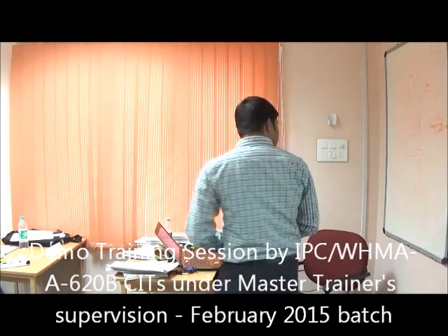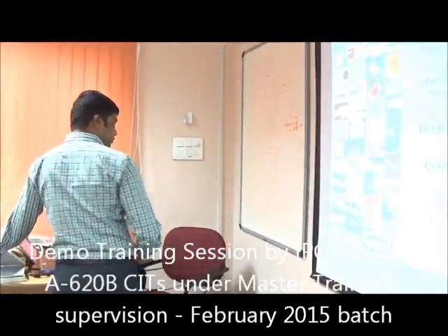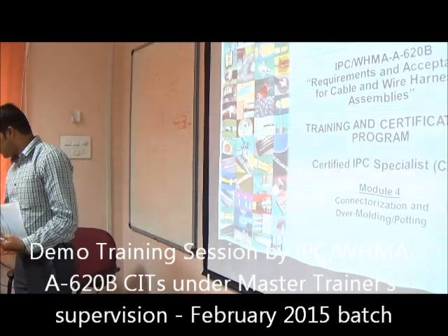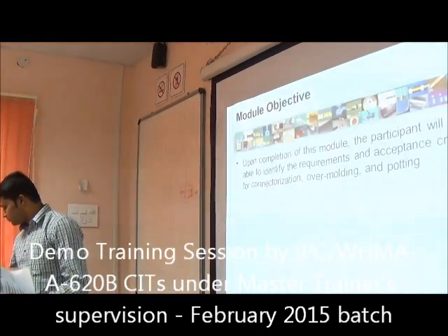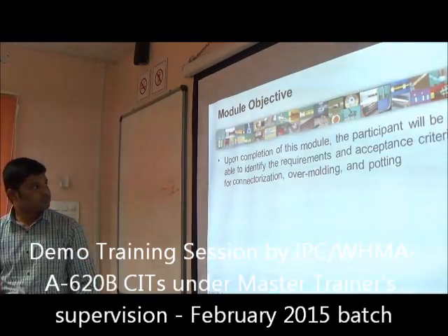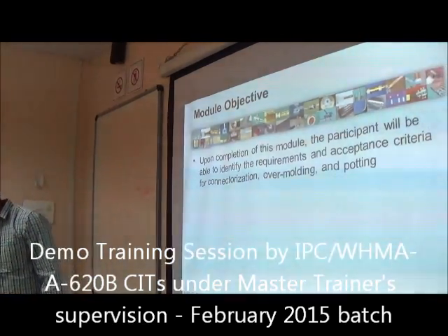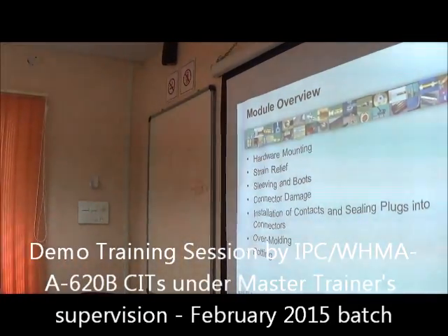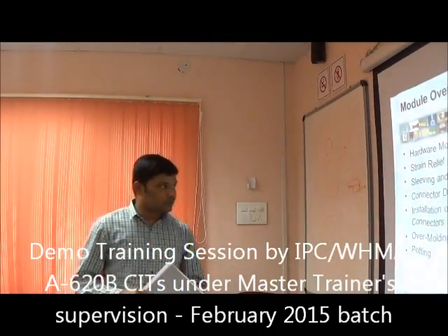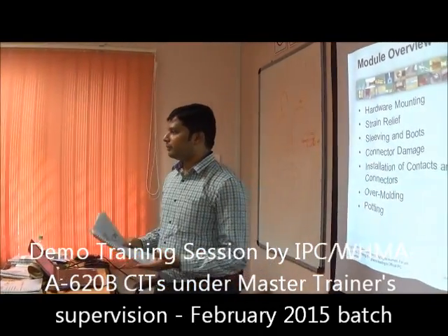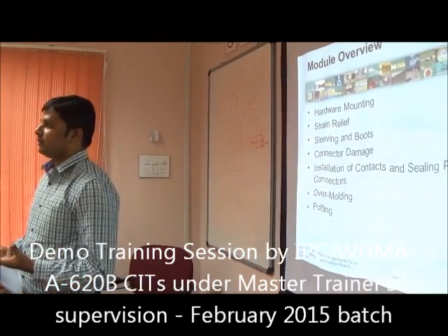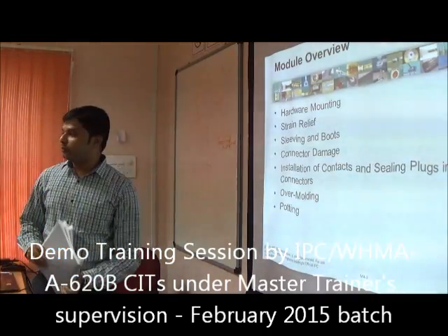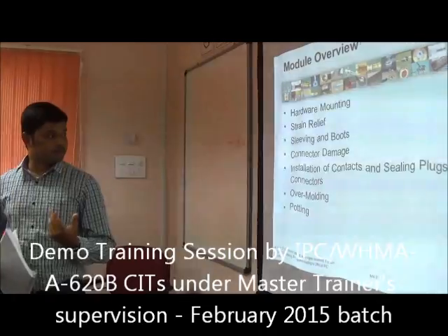So in this particular section, in module 4, which covers section 9, we will be dealing with hardware mounting, like installation of jack post and jack screw, followed by strain relief. In strain relief, basically we use the strain relief for avoiding stress on the wires, followed with sleeving and boots, which will be mounted over the ferrules.